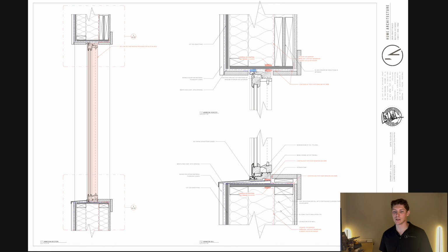Like these air barriers, like this insulation. If the client told the contractor, I'm just looking to build a 2,800 square foot home, and we hadn't discussed any of these details, and then they came to them later and said, actually, I want to do a double 2x4 wall with interior air barrier and an exterior weather protection system with continuous insulation, all of those things would be a little bit more complex than your standard home.